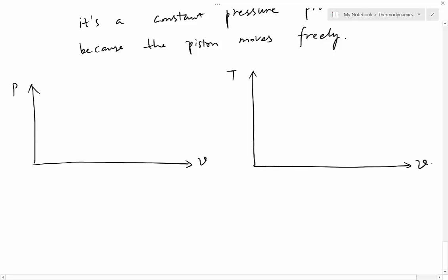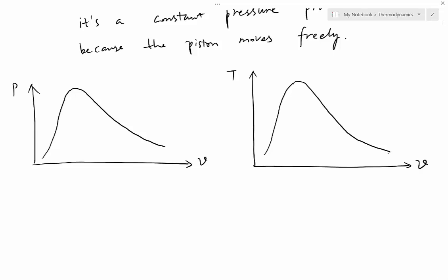Whenever you use the two diagrams, the first thing you do is always the same, which is to sketch the vapor dome. Remember, steep and then less steep. Same thing, steep and then less steep. So the first thing is always the same: sketch the two vapor domes.